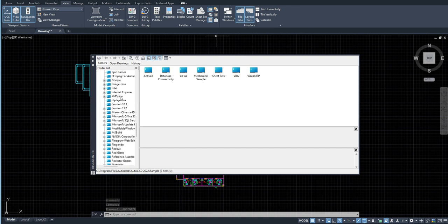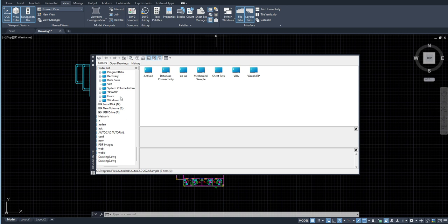I'm just going to have to select the drawing file. For example, I select drawing 2, and you can see all these different options available over here. For example, blocks, detailed view, dim styles, layers, layouts. So not just blocks, you can import all of these different items from a different drawing file, but for now we are talking about blocks. So I'm just going to select blocks.